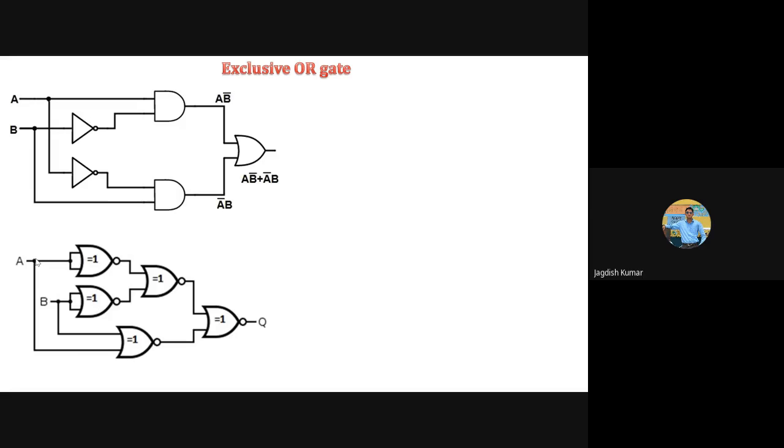Well, then if you take what was B, B was 0 and A was 1. So B 0 means and A 1 means output here is 0 once again, because B is 0, A is 1. So 1 means this is NOR gate, so output will be again here 0. So both will be 0, 0. What will be the output here? 1. So Q will be 1. I'm sure you are not uncomfortable with this.